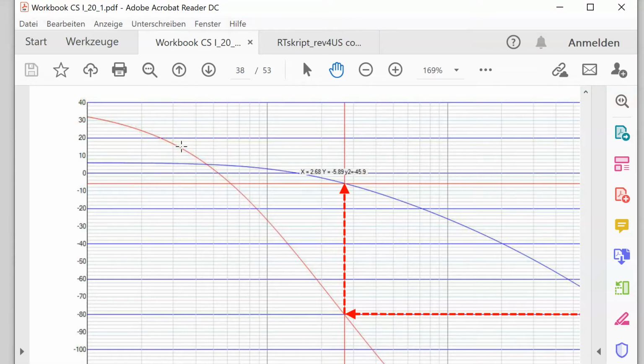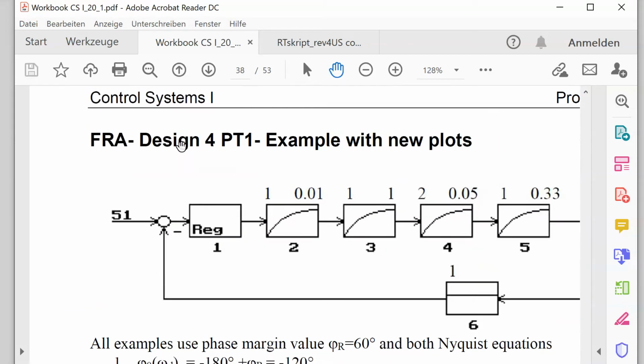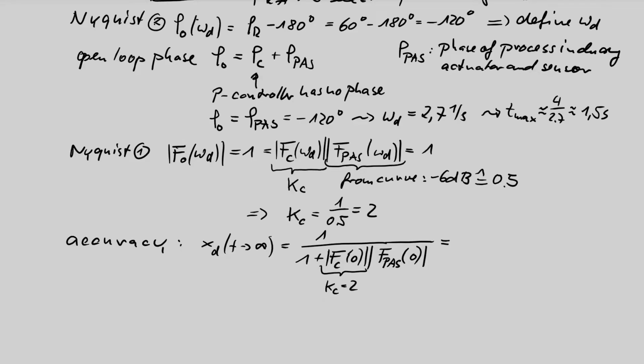Okay, we know the signal block diagram of the system, and I have told you that the DC gain from block 2 down to block 6, the DC gain is 2. So yeah, this fits to our knowledge, but note that only the Bode plot is given. This is normally not known, but in our case we know the DC gain of the process is really 2.